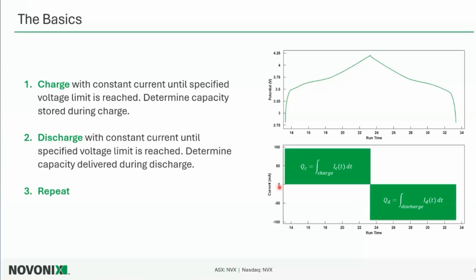And now the trick with some of these pieces of information is if your measurement of current and voltage isn't accurate or precise, through these raw data measurements of time, voltage, and current, then this error or uncertainty kind of propagates through these calculations. You're integrating over all of these errors. And if you're over counting during charge or under counting during discharge, these deltas really add up, and this can really affect things like coulombic efficiency.